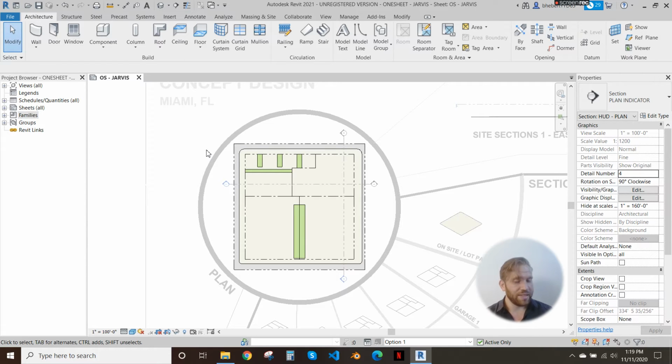I don't like to use massing or the massing tool or a massing building tool. It takes longer, and you have a really complicated building design or master plan design that has multiple uses, mixed use, garage, podiums, that type of thing. I've found that using ceiling families on a very simple building block level is the way to go. So that's part of the unique part of this experience. So bear with me and let's dive in.